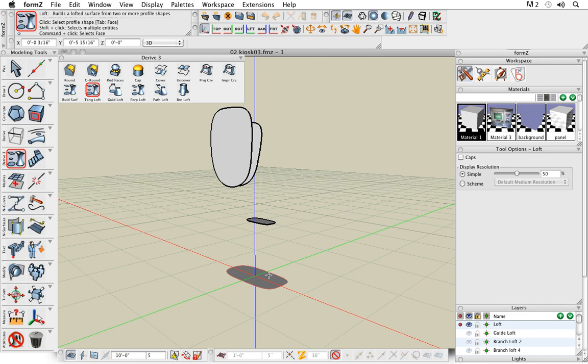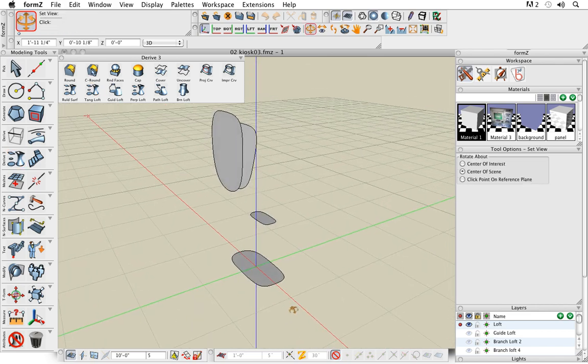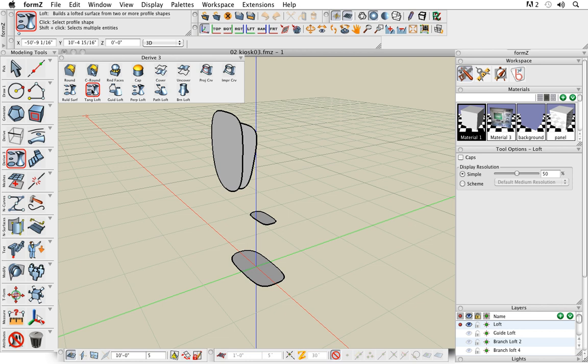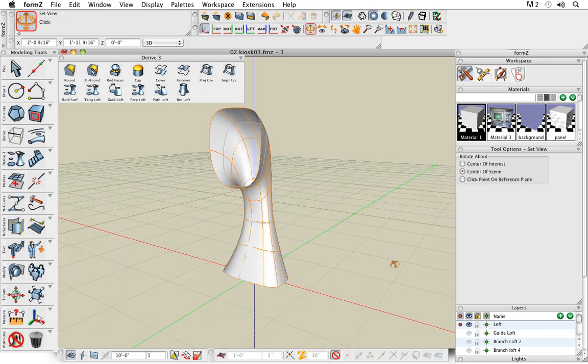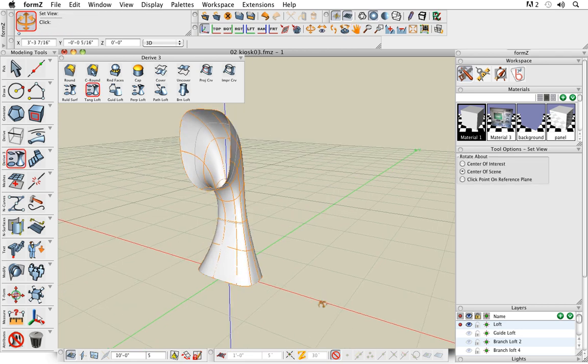So we'll begin by creating one of the kiosks, which is just a bunch of 2D cross-section shapes, and we already know how the tangent loft works, right? You just simply hold down the shift key, pick a bunch of cross sections, and you can create a nice little tangent loft through those sources. So that's a normal lofting operation. We also use the tangent loft to create the skylight by clicking on outlines and edges of objects too. It works using both methods.